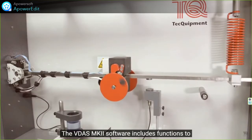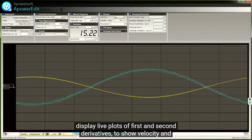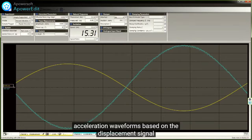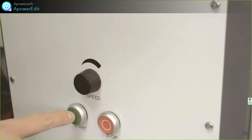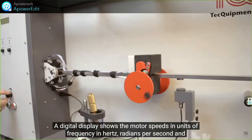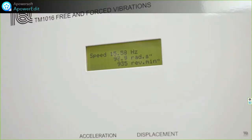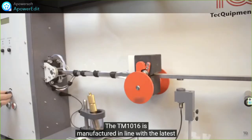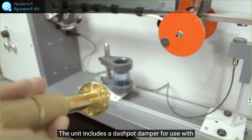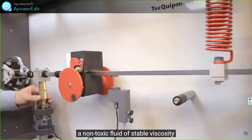exciter. The VDAS Mark II software includes functions to display live plots of first and second derivatives, to show velocity and acceleration waveforms based on the displacement signal. A digital display shows the motor speeds in units of frequency in Hertz, radians per second, and revolutions per minute. The TM1016 is manufactured in line with the latest European safety standards. The unit includes a dashpot damper for use with a non-toxic fluid of stable viscosity.